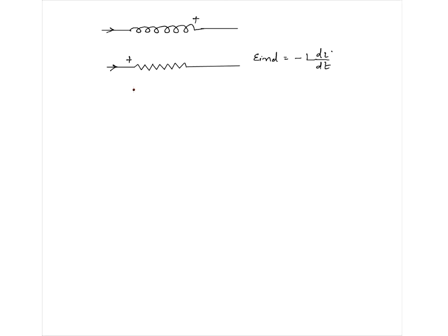So this was for resistance, this is for inductor. But for inductor it is about change in current. For resistance it was not about change in current, it was about the current. Whatever current is, this will be plus. Here, if current is steady, the 2 points will be equipotential points for ideal inductors. If there is no change in current, that won't be so for a resistor.